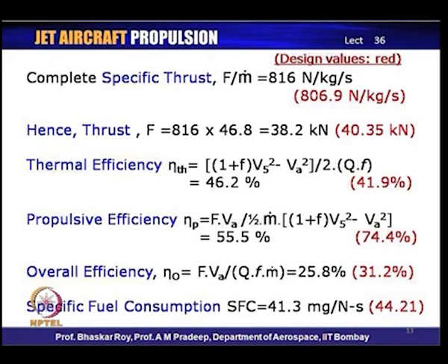Now, again mark here that this thermal efficiency is indeed a little more than the thermal efficiency of the engine at design point. This higher thermal efficiency also stands to reason, by the fact that at off design it is operating at a higher pressure ratio. This higher pressure ratio indeed yields the higher thermal efficiency, and we had seen that it also gives higher specific thrust.